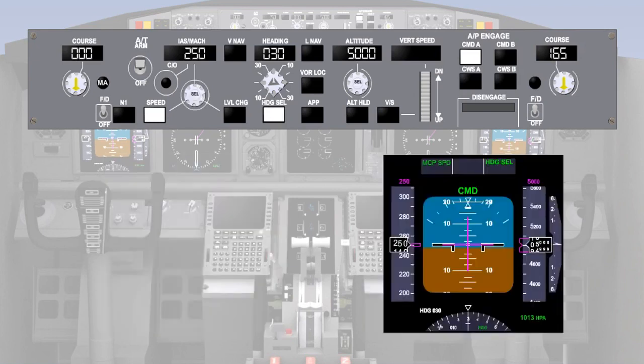With the autothrottle maintaining the speed in speed mode, altitude hold can be engaged in pitch. When the altitude hold button is pressed, the light in the button illuminates, and Alt Hold is enunciated in green in the pitch window of the flight mode annunciator. The autopilot pitch channel will now maintain the altitude, with the autothrottle maintaining the speed.